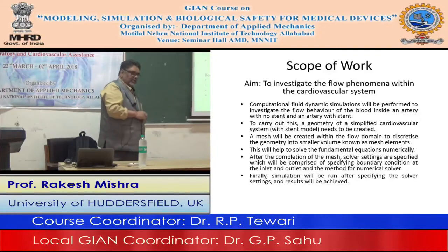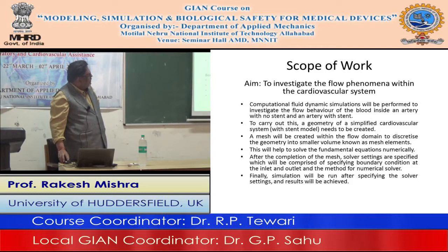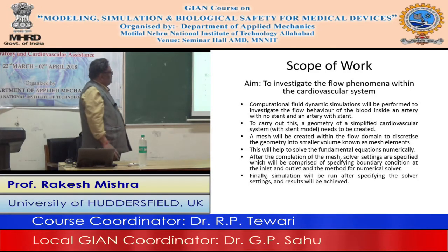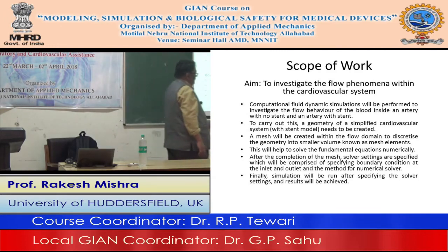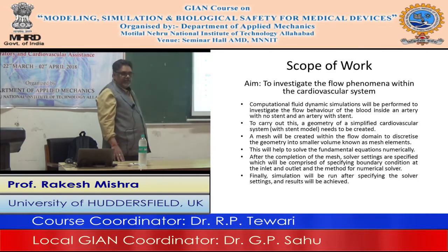Itself affects the flow, that we'll study. But apart from that, we'll be running two different types of conditions. The first thing is we'll run a steady state simulation with inlet pressure here of 3000 pascals, but then we will try to vary the pressure using a user-defined function.